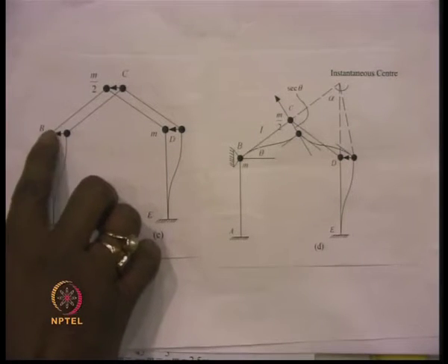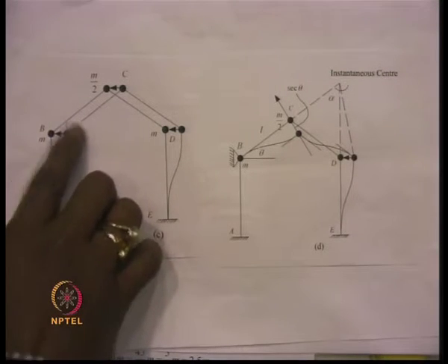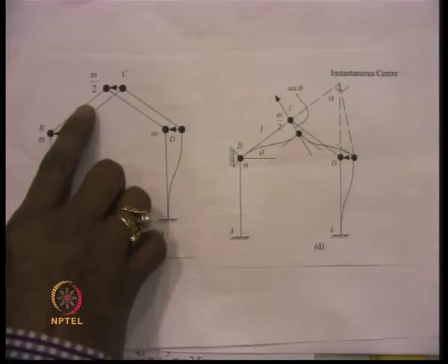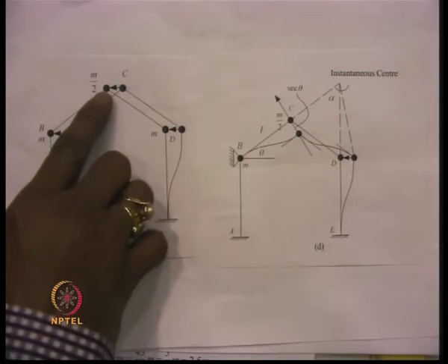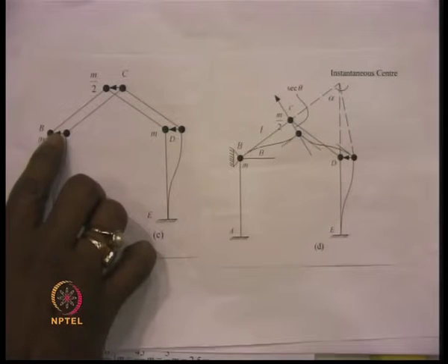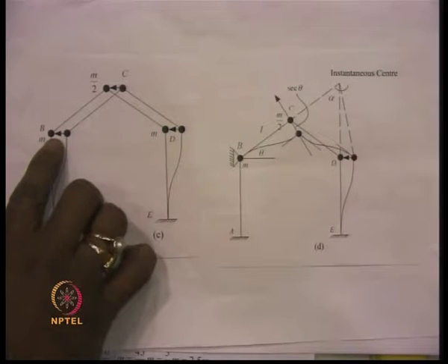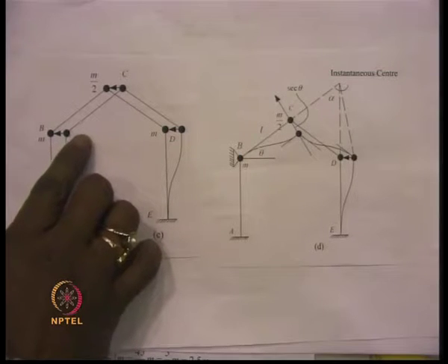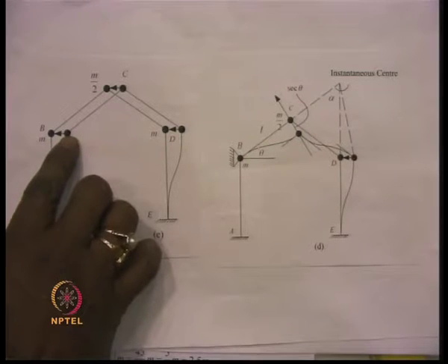The forces existing over here are three forces. One force is this one, plus the two forces which are the components of the forces coming from this point and resolved in this direction. These three forces are added together, and by definition would be equal to M11, that is the inertia force produced at this point due to the unit acceleration over here.